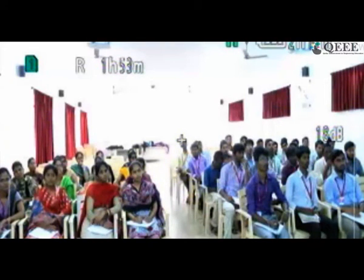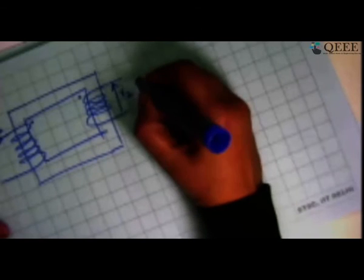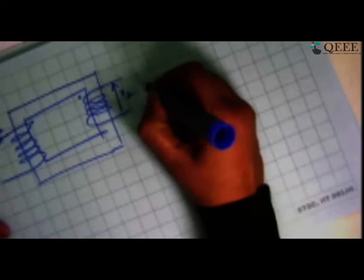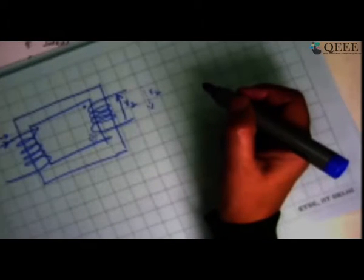If the winding voltage is in such a way that the voltage rise is shown in this direction, then I would say the dot is here. If the voltage rise is shown in the other way around, like dotted line what I have shown, then I should show the dot here. Where the dot is depends upon the orientation of the winding.